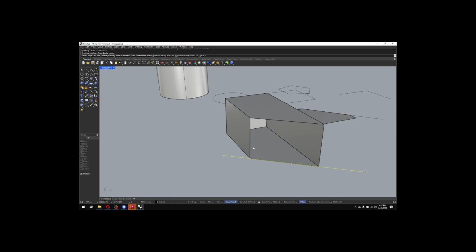So you got to be careful if you want to trim but leave something solid, we have to use a different command. We're going to touch on that one here in a second. But if you just need to cut a piece of anything off, trim command works.